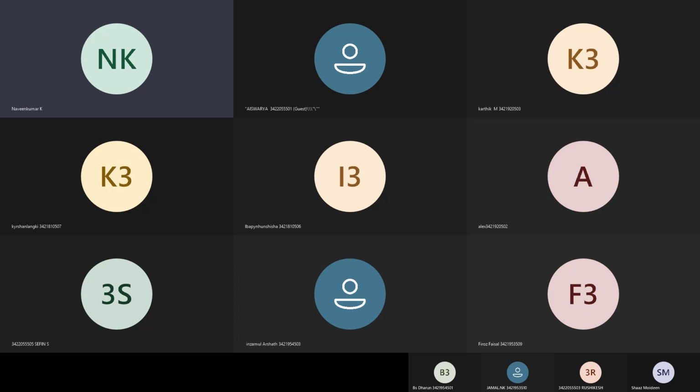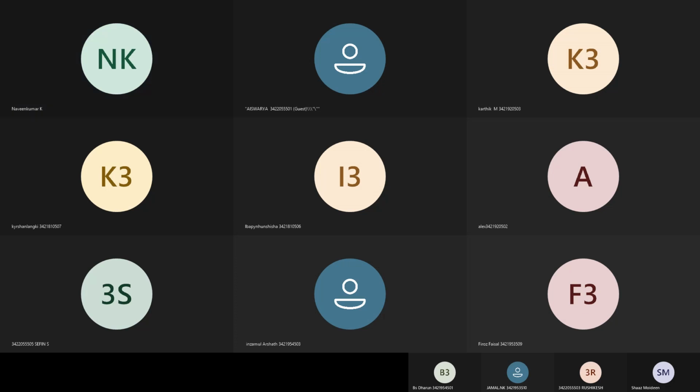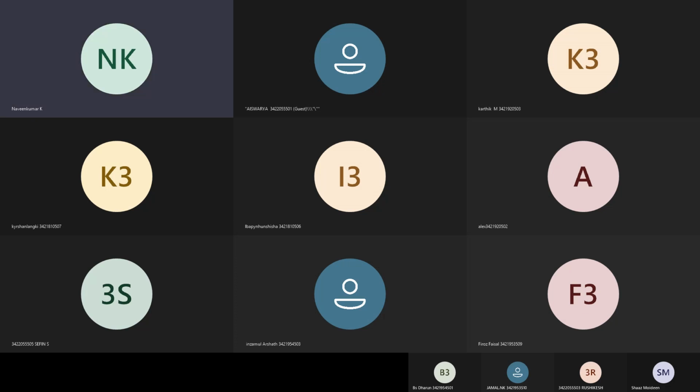Based upon the load intensity, we ensure whether the depth of the slab which we assumed initially is correct or not. If your assumption is right, you can go with your assumption itself. That we have ensured. After that, we did the reinforcement calculation based upon the moment along the longitudinal cross section as well as along the transverse direction.